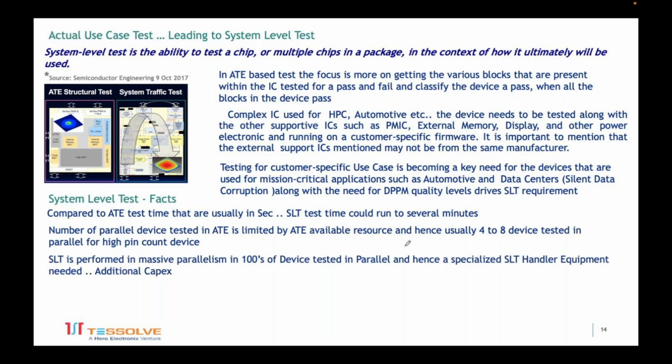Whereas in SLT, the test times could be in minutes. So definitely parallelism is one of the key things. Here you're trying to test hundreds of devices. Of course, it doesn't use any of the ATE resources, but you need a specialized handler for that, and that will call for an additional capex.